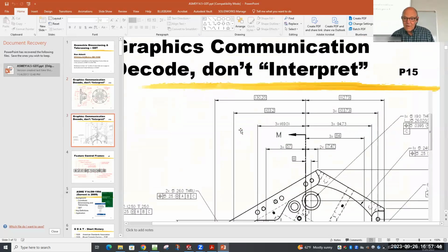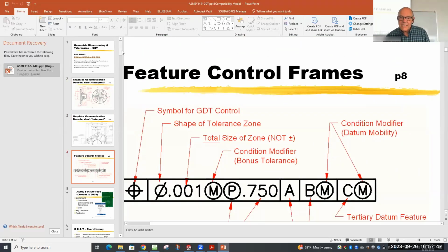Now, this shows up on, do I have a drawing of that? Well, it shows up if I did a drawing of this, because I tell you that's 30 degrees, but that 30 degrees would be in a box. Perfectly 30 degrees. What's the variation permitted? There's a sandwich that's 30 degrees. So I got my two pieces of bread and I can somehow make them exactly 30 degrees. And the space between the two slices of bread is whatever number I put in the tolerance for angularity. Now, if the entire surface fits between those two surfaces, everything's fine.